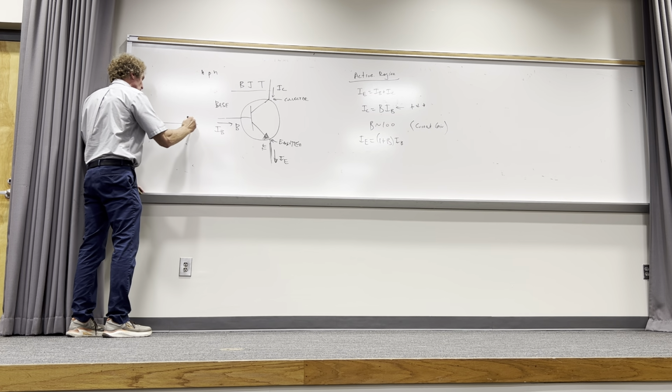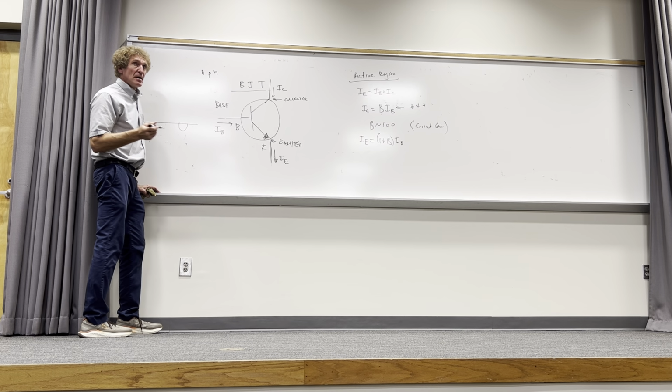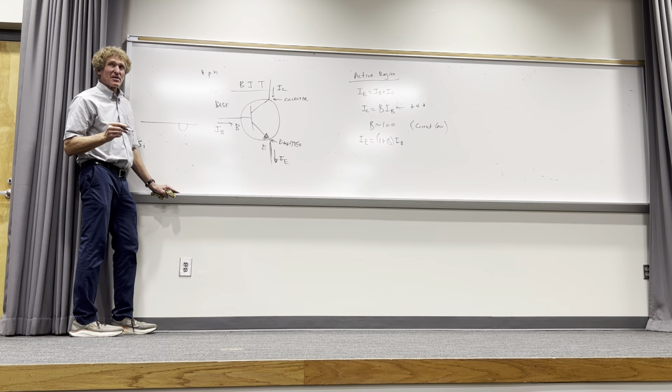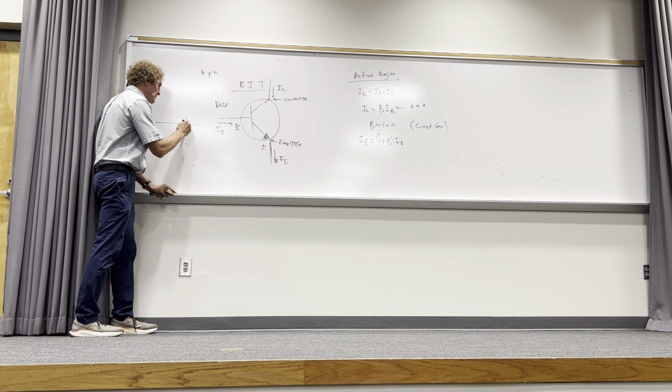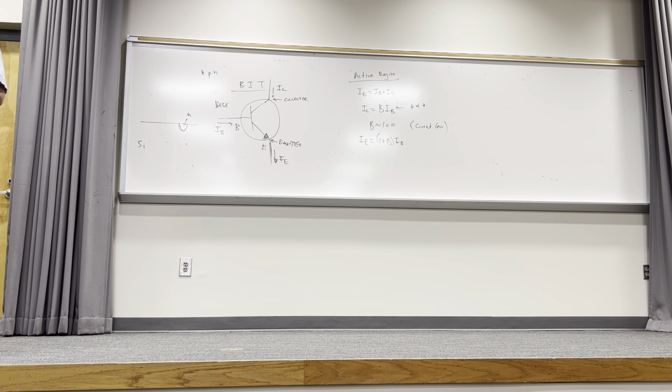This is actually the way it would be made. There would be a small amount. This would be a silicon bar, and I'm doing it in a very basic way. And there would be something here that's called a diffuse junction that would have N-type dopants. It means there are more free electrons in what I consider the conduction band.